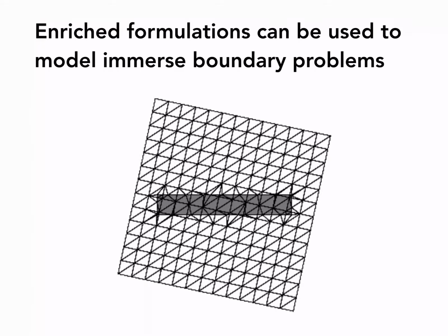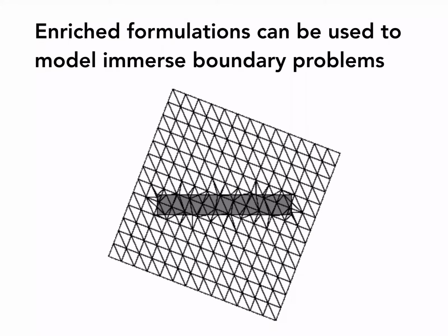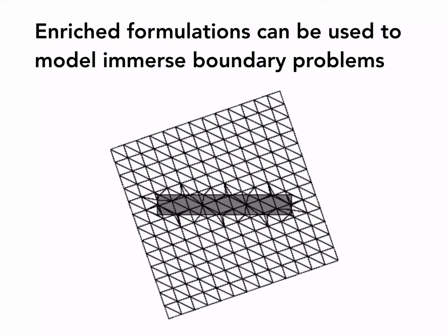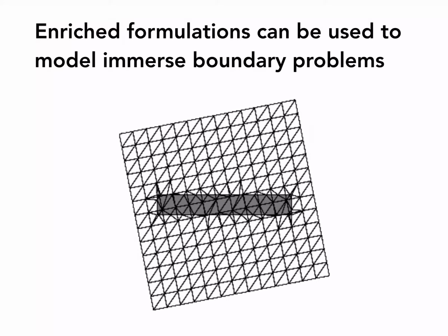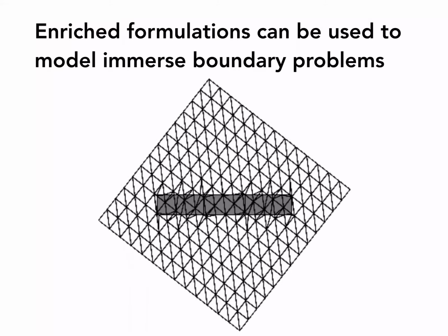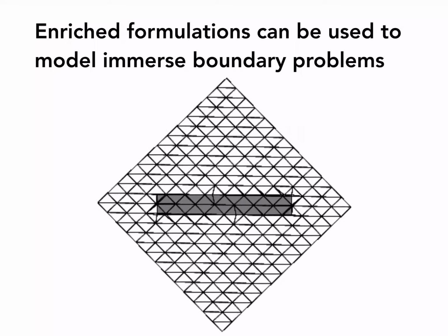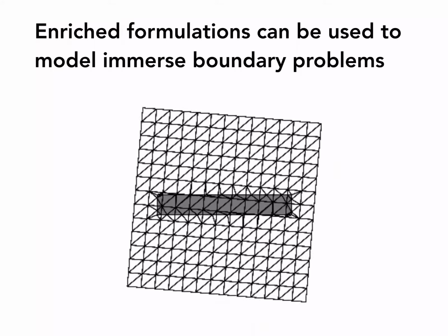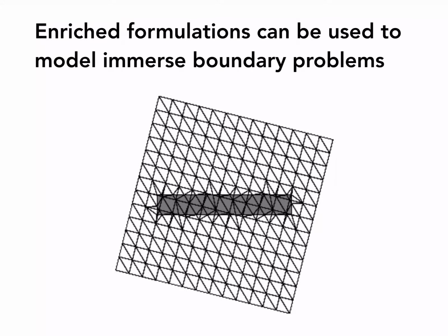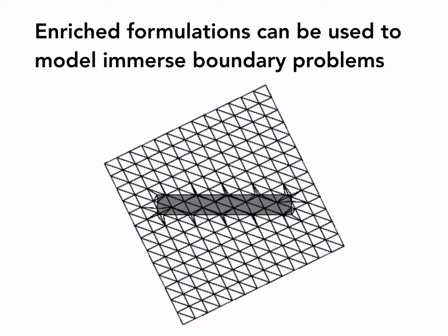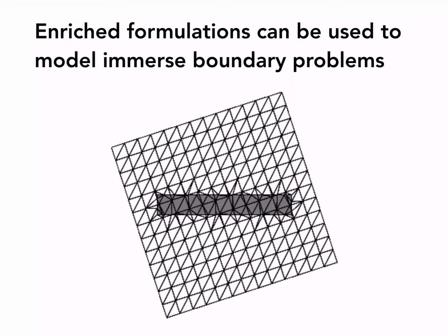And I'm not doing refinement. It's very important that you understand that there is no refinement here. I'm actually using the original shape functions of a parent mesh, the original mesh, and all those little triangles that you see are called integration elements. So those are elements that are created just for the sake of integration, okay? But you are still using the original finite element space.